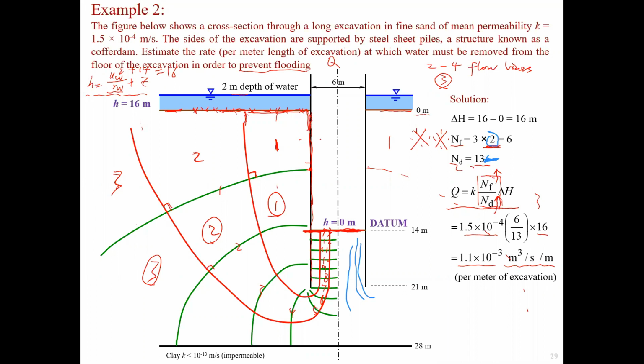No, this one no need, because that's only the head drop. That's not flow tubes. For flow tubes, you see the left-hand side and right-hand side, so you have to consider the sum of both sides. But head drop is only the relative level from the upstream to the downstream, so you only need to use one value.